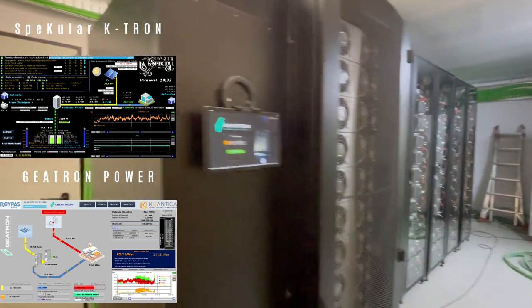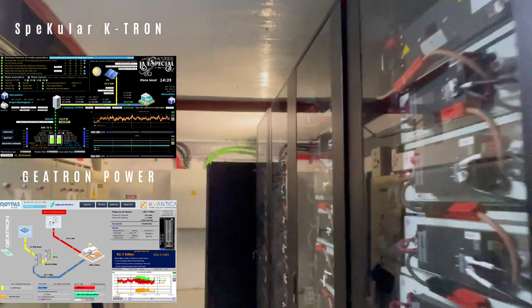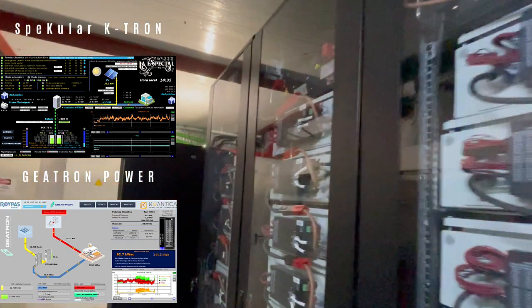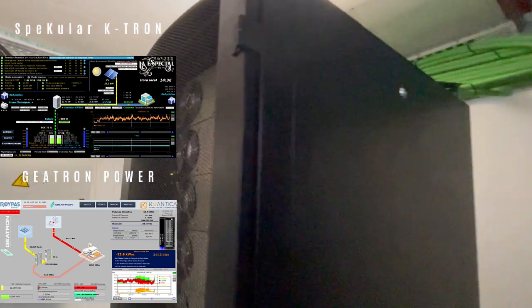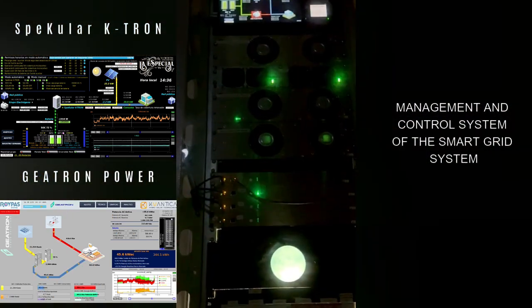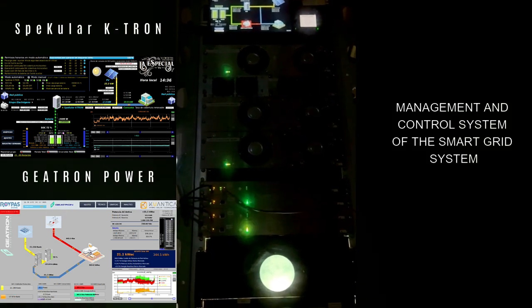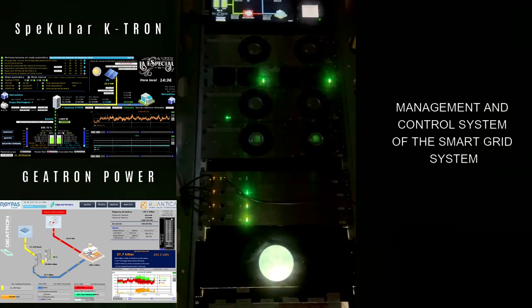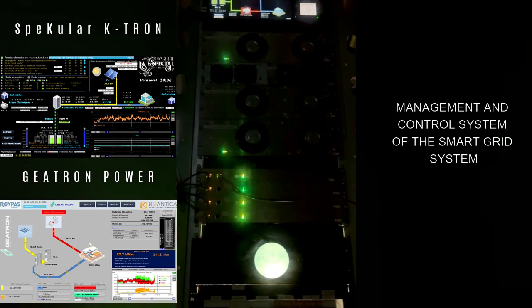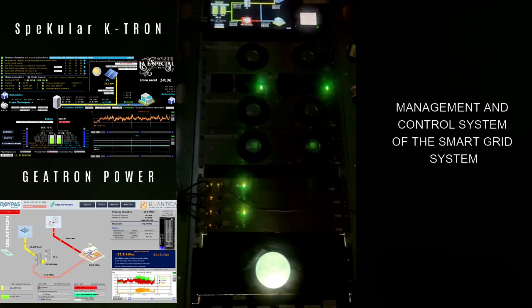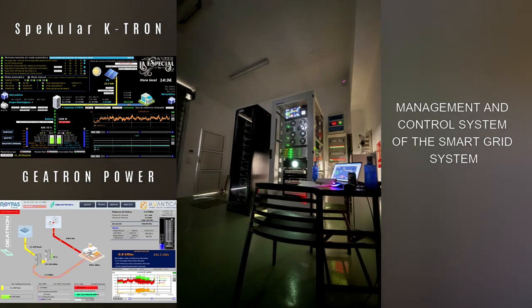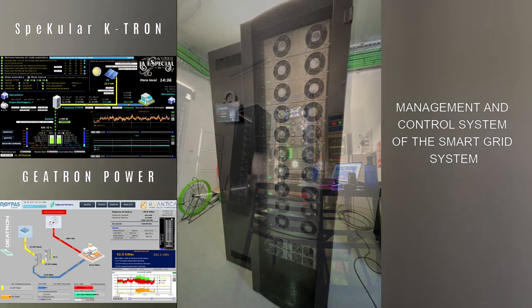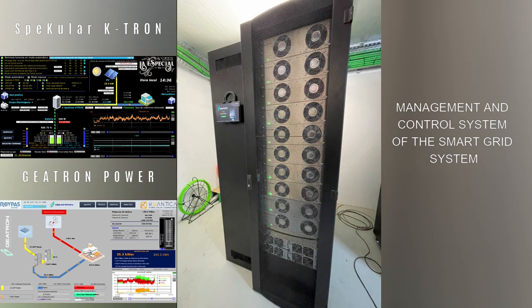Control of all necessary actions of the auxiliary grid supply equipment, generator set. Manual and autonomous on-off switch with the ability to self-manage, with the ability to autonomously and independently manage events. Autonomous management of the change between the different operating modes required by each of the components depending on the operating mode required at any given time. Parameterization of all parameters associated with battery operation, with the possibility of parameterizing values for different storage technologies. Can be operated entirely locally through the proper use of the documentation provided.